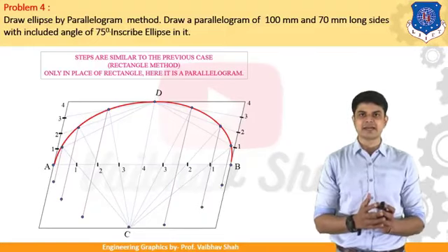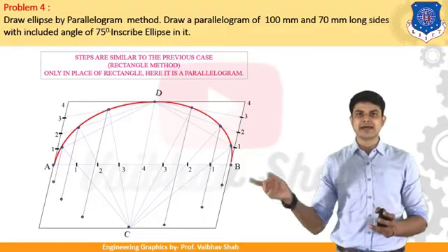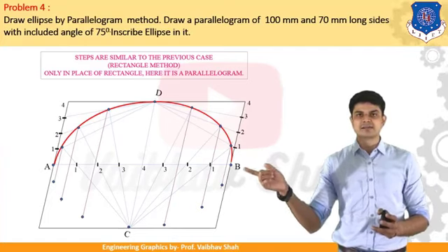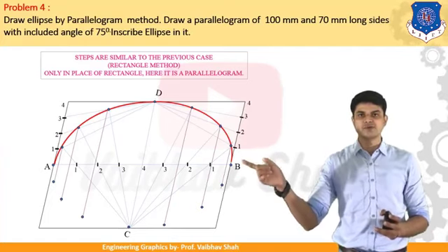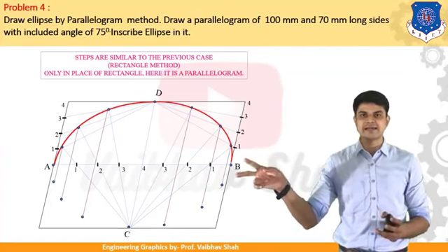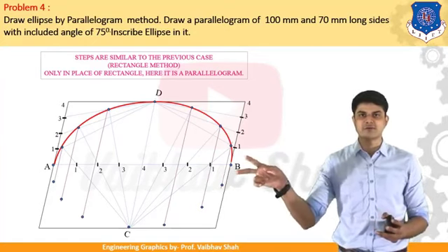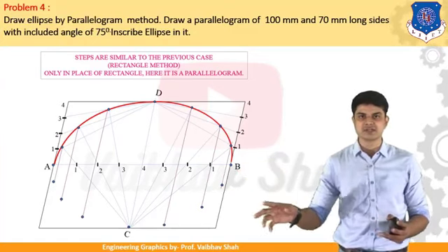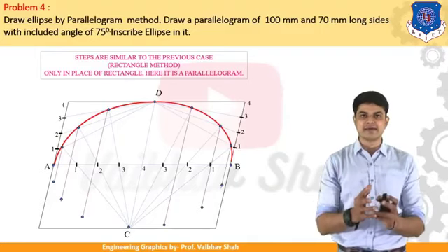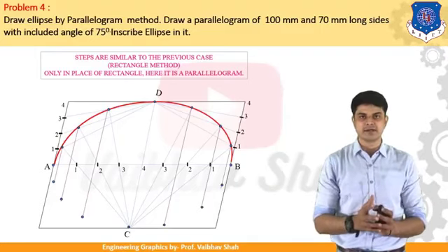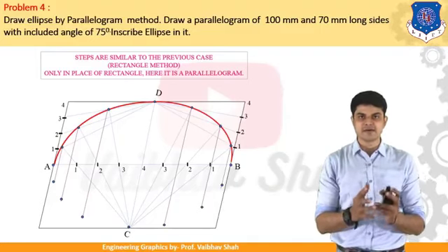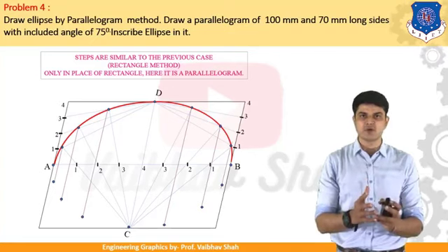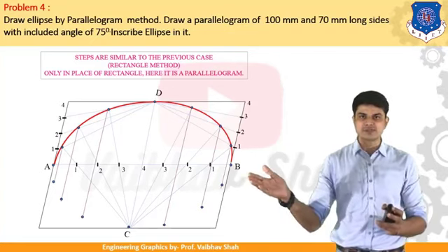So let us suppose I take one example. See, this is the line starting from your center axis till your 1 point. So you need to take the dimension of that line, and you need to produce the same dimension from your center line in the downward direction onto that line, and you will have the end point as your ellipse point. So here we are defining one center line. The center line in this case is AB.